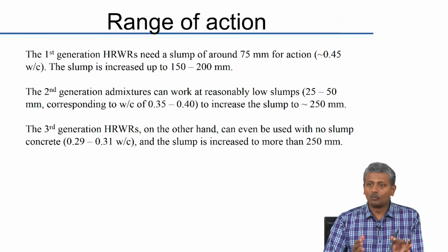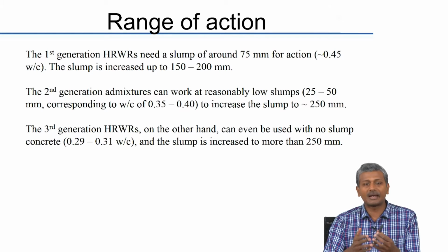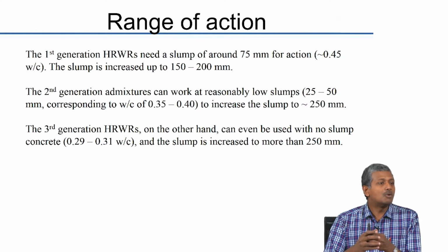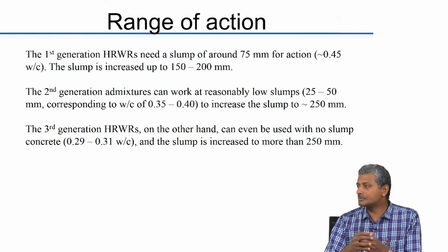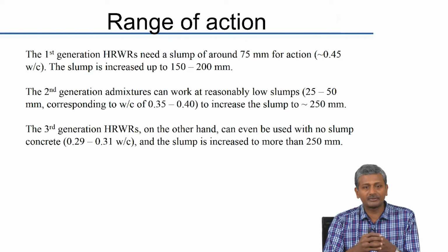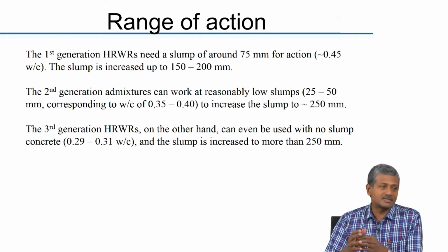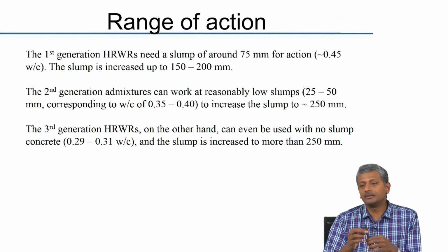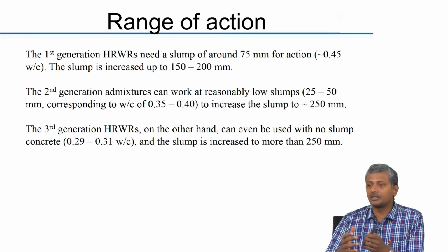Okay. Now, what we saw so far was what are the different mechanisms of action of different types of superplasticizers, how effective are each kind of superplasticizer in giving a specific workability for your concrete mix. We also saw what you can do with simple test methods to assess the combination of paste and cement and superplasticizer and determine the suitability for making the concrete.